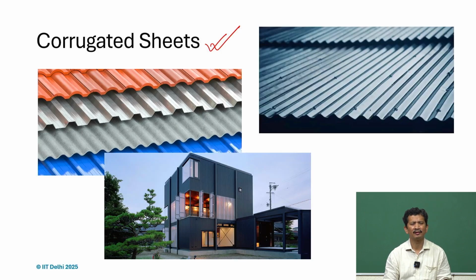These days these corrugated sheets are used very widely because we now have many designs, many alternatives. Aesthetically also they are very good. So, we can make even warehouses, and some architectural firms even design homes using these corrugated sheets. The only reason we find this wide application is the strength, and that we get mainly because of the corrugation.